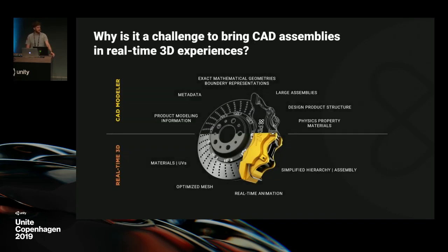First, a little bit about CAD, because it's important. Nowadays, CAD models are everywhere, because almost any manufactured product is primarily designed in a CAD solution like CATIA, NX, or Alias in this case. But it's not easy to turn CAD models into real-time visualization material, in particular large CAD assemblies. CAD data is meant for design, engineering, and manufacturing, and it usually comes with a large quantity of information. If a car is composed of hundreds of thousands of parts, you can imagine how huge a CAD assembly can be. The main differences between CAD and real-time 3D data are the geometry, the assembly tree, and the materials.